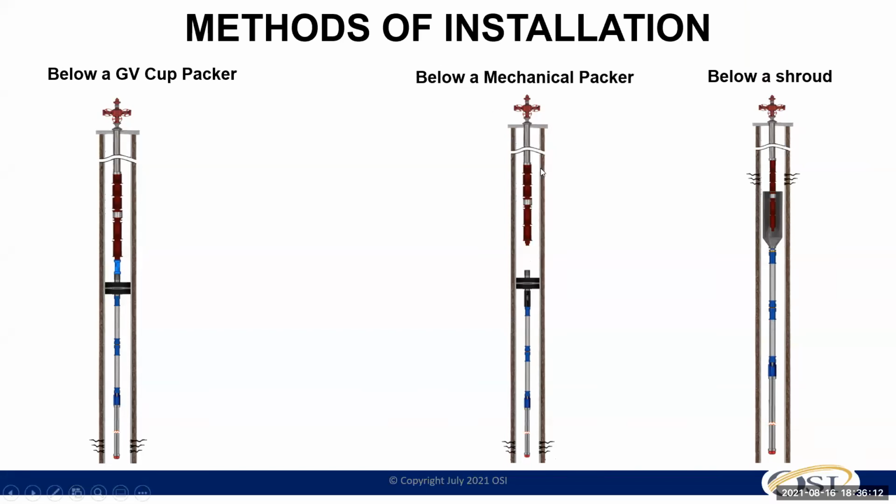Yes, sir. How can I prevent the sand from entering the downhole pump? So that's what I was saying on this one. You have to select the right method based on your perforation. The way you can control that is you have to isolate it. In this case, if that is an ESP, that's where I use this method with the cup packer.